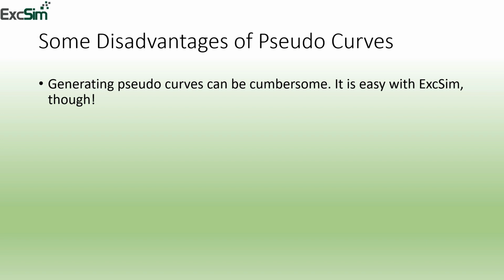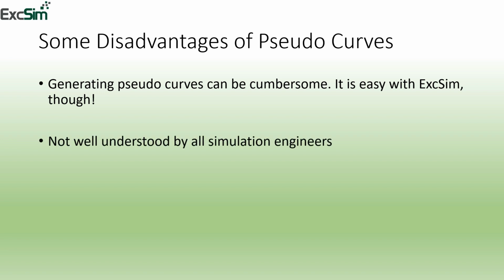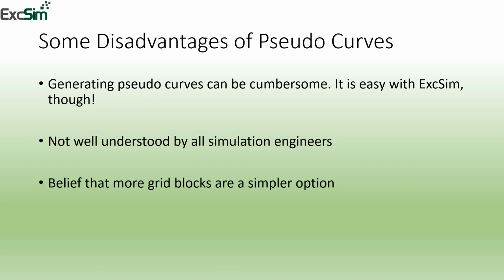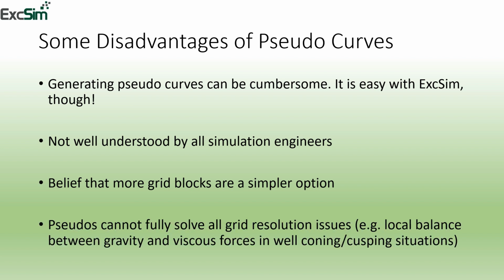Some disadvantages are that generating pseudo curves can be cumbersome. With ExcSim, it's very easy. I'll show you. And pseudo curves are not well understood by all simulation engineers, and there's a belief that more grid blocks are a simpler option. Pseudos cannot fully solve all grid resolution issues, such as local balance between gravity and viscous forces in well coning and cusping situations.